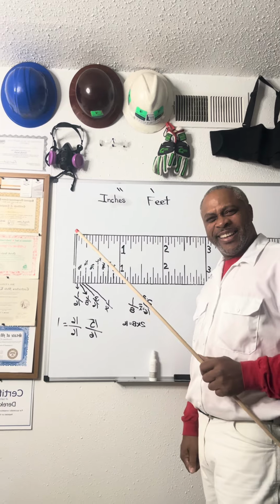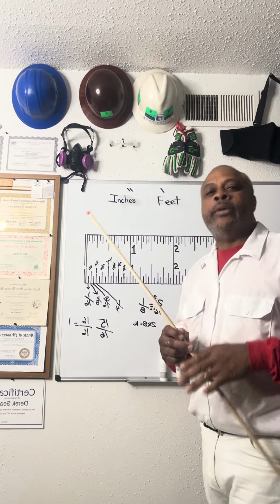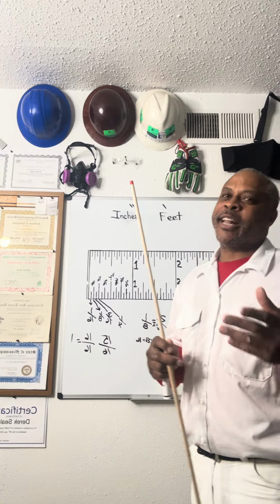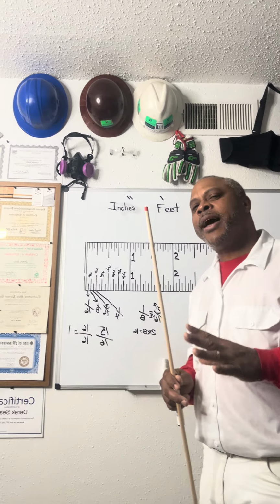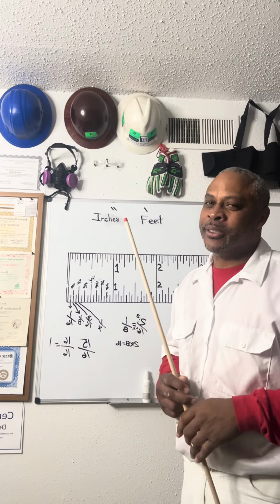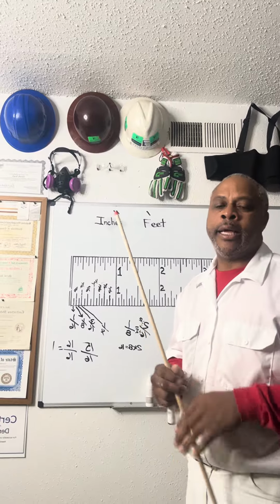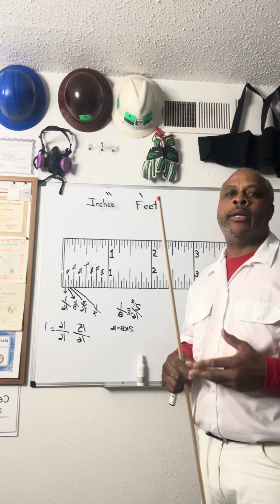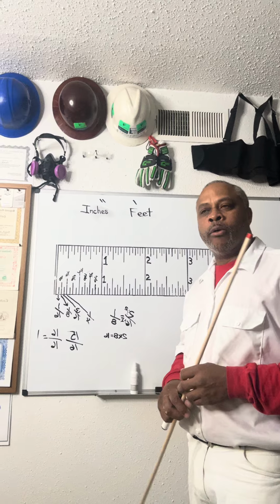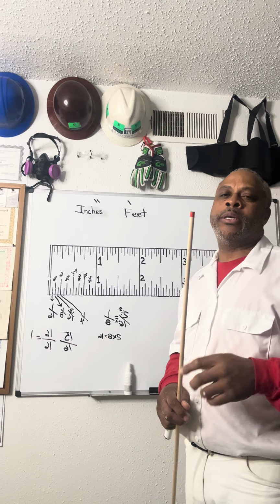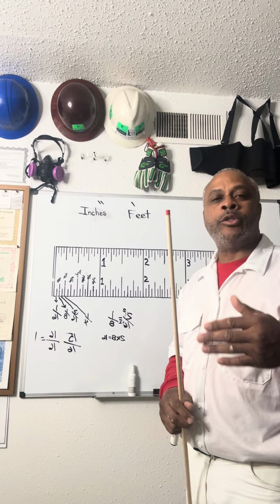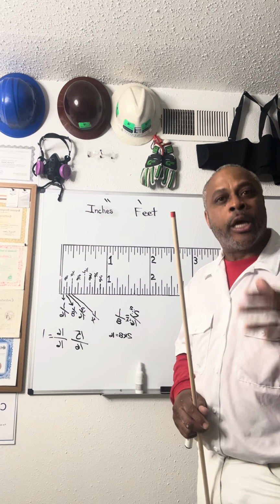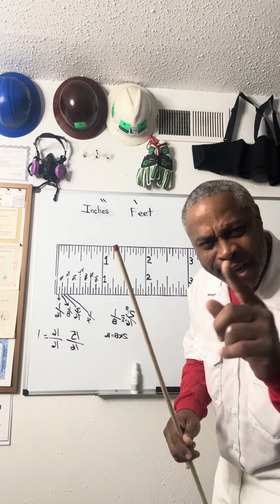Why is that? Now we're getting into milling. Just like a 2x4, 2 inches by 4 inches, there's not really 2 inches by 4 inches. It's because of the milling. They have to mill it down after they've logged the wood. So a 2x4 is usually 1.5 inches by 3.5 inches, and all the various lumber sizes. We're going to get into that, but you've got to stay with us.